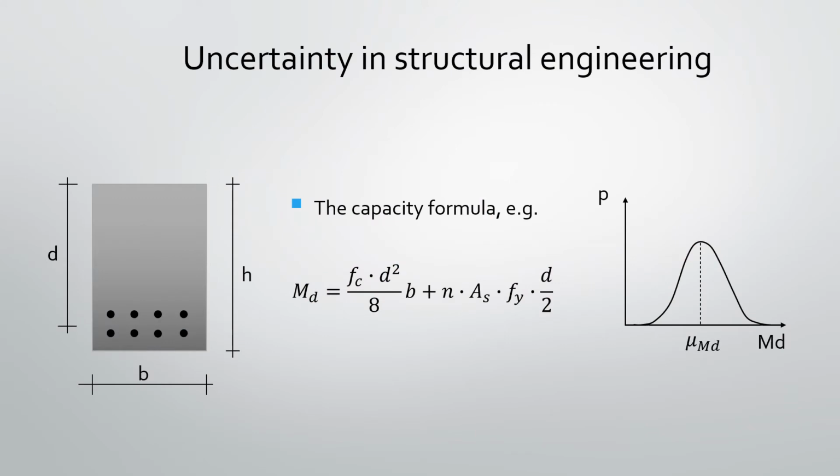Even if we perform careful tests and measurements of the mentioned parameters, and use these carefully obtained parameters in a capacity formula, we will still not be able to accurately determine the bending capacity of the concrete beam. If experiments in a laboratory are performed, they will still show some variation. All this variation has to be included in some way when we predict a safe bending capacity of a beam. For a specific beam, this variation will be uncertainties. Even if we know the probability functions for the variation for each parameter, we don't know which value of the parameters was drawn for this specific beam.